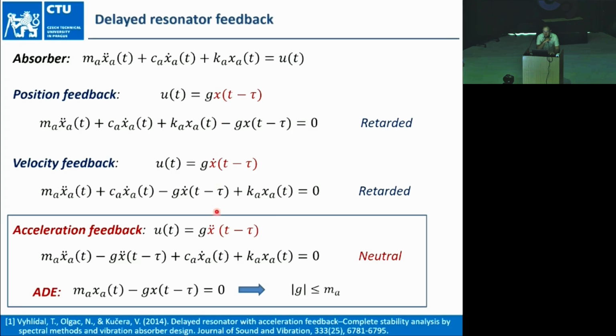So one could ask why a time delay algorithm? Could we use, for example, a PD algorithm? Of course we could. We just need two parameters to tune and place the root at the imaginary axis. But the time delay feedback has some advantages because we just need a single measurement. In the case of PD, we either need to measure both position and velocity, or somehow derive numerically the velocity from the position, for which you need to introduce a filter, and you deteriorate your performance a bit.